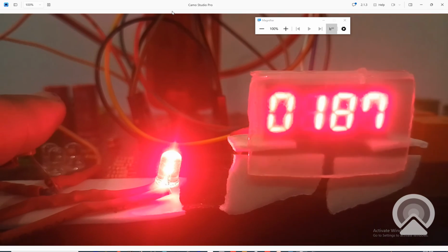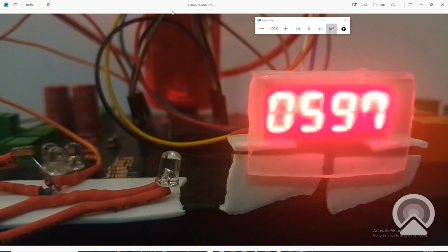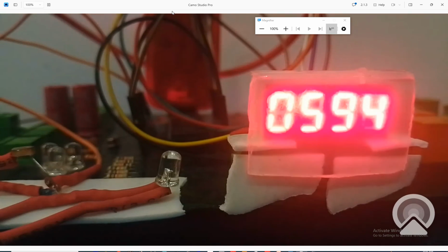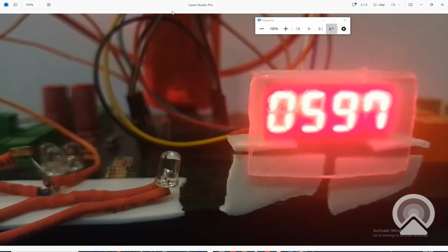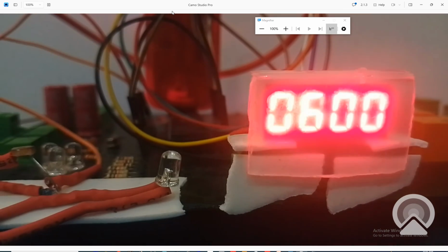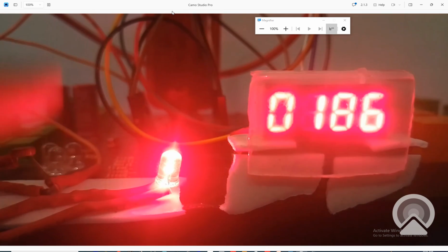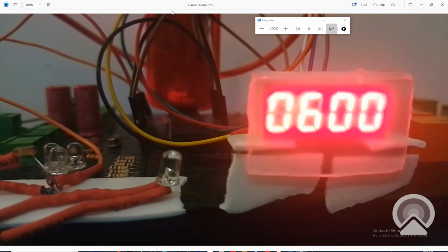So whenever the finger comes in front, LED turns on. It indicates that finger has been detected. Or it's dark in the room. LED on means it is dark in the room. Like you make a light, whenever it goes dark, the light turns on. By default, the light of the room is 600. So you can use it as a threshold. This segment will be very useful for making a threshold. See, I place a finger, it turns on the LED. By default, the value is 599, 600.